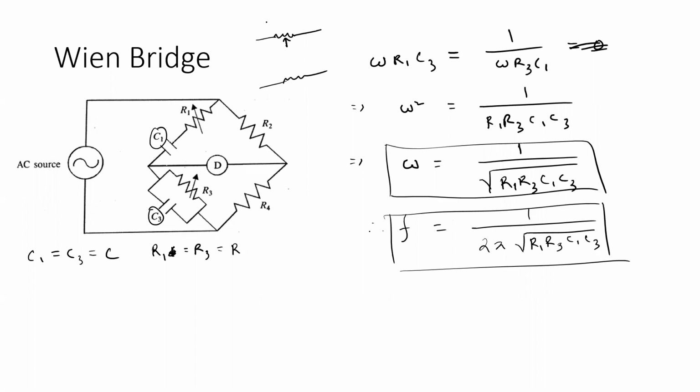Suppose this is R1, this is R3, and this is the slider of the other variable resistor. Suppose both of them are 10K, and if these two sliding arms of both the variable resistance can be coupled together, then whenever the slider is varied, as both of them are coupled together, they will give the equal value of R1 and R3 each time.